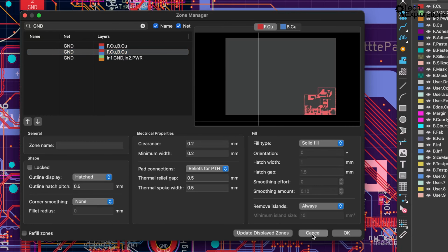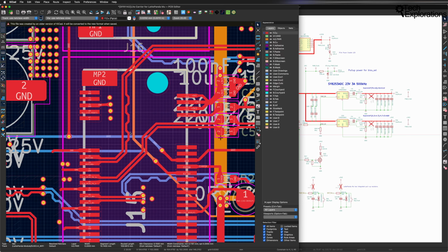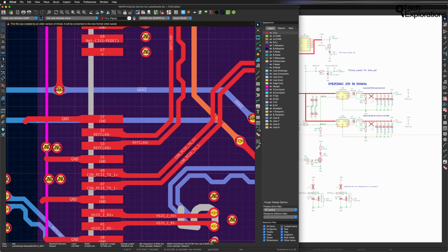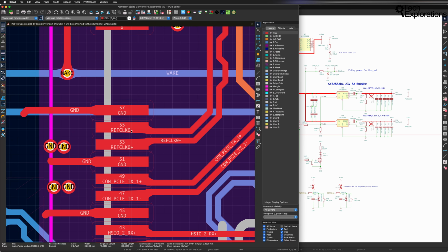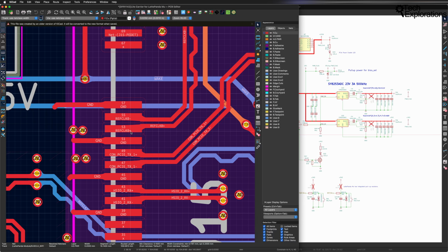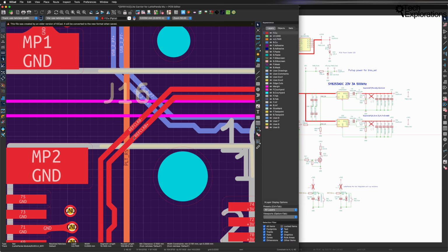The differential pairs, if you're not familiar with the concept, are lines such as this one here. So zoom in, you can see this is one of the high-speed interfaces, and we've got these two pads that propagate through these two traces and lines. You can see one is marked with a minus, the other one is marked with a plus. These work together, and there are specific characteristics that have to do, for example, with the spacing between the two lines, the width of the lines, or tracks.